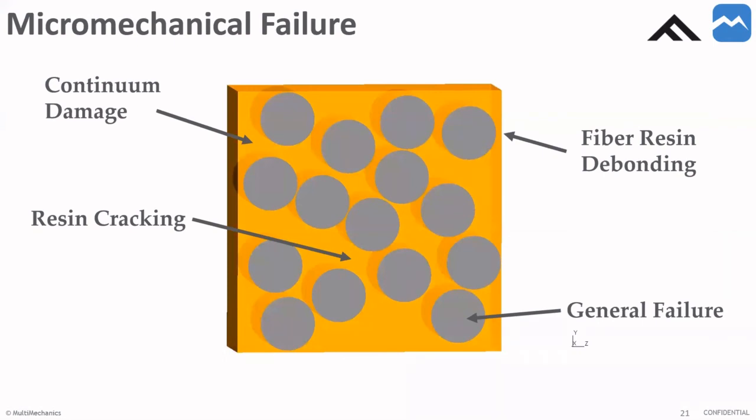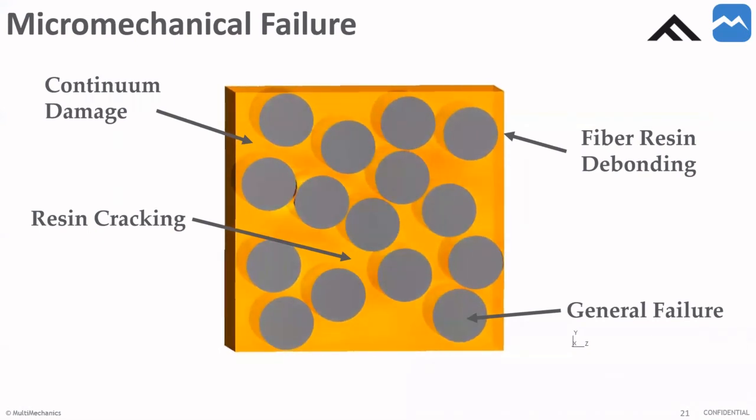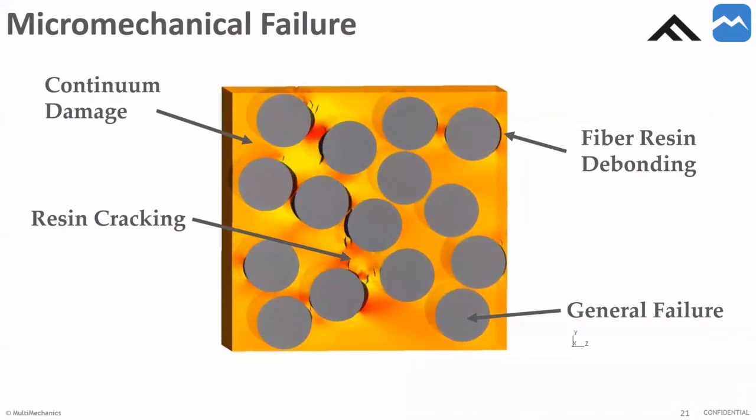The optimizer, and Dan touched on this very briefly, can run simulations overnight without actually having to make changes to it. We'll take an RVE like so, run it through the optimizer, and it'll change the fracture properties of the FEA code until we calibrate on a certain value, and we can match that value to composite properties.